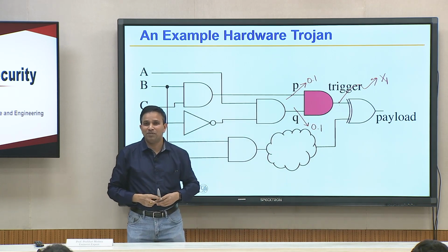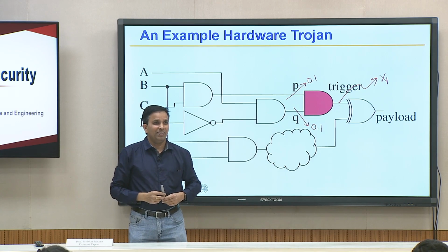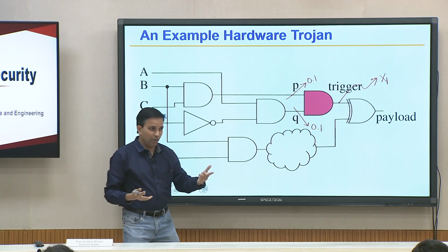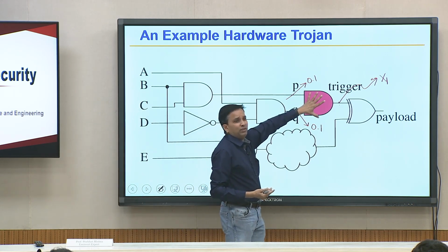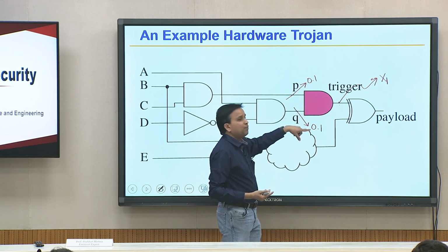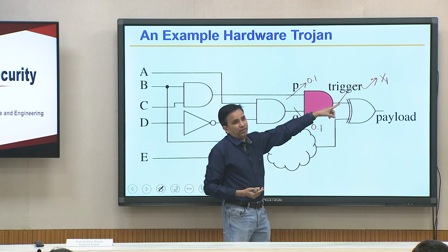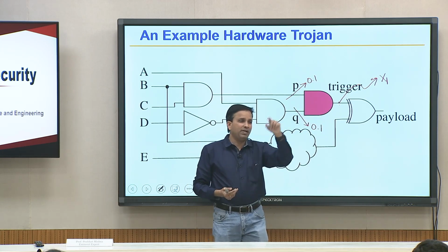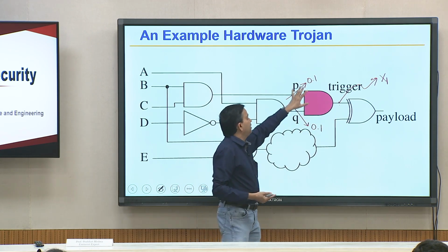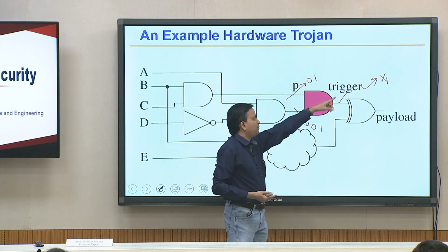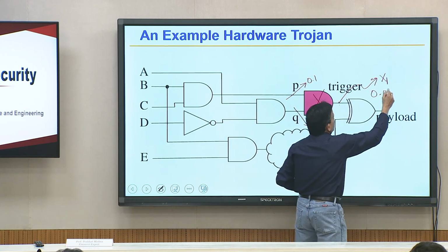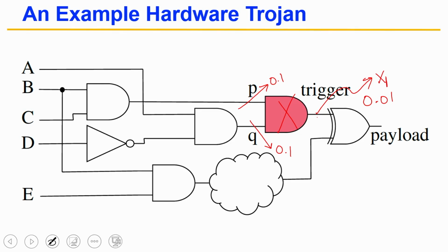You already saw the static computation, right. Is this dependent or independent probability? First, this is dependent probability. Even if you did not know this gate, it is still 0.1 times 0.1, so it is going to be 0.01. But if you know this is an AND gate, then from the truth table you saw, 0.5 becomes 0.25, but typically it is 0.1, 0.1. If you do not know the gate, then it is going to be about 0.01, simple multiplication. That is not accurate. Now that you know it is an AND gate, you have to do the truth table thing.